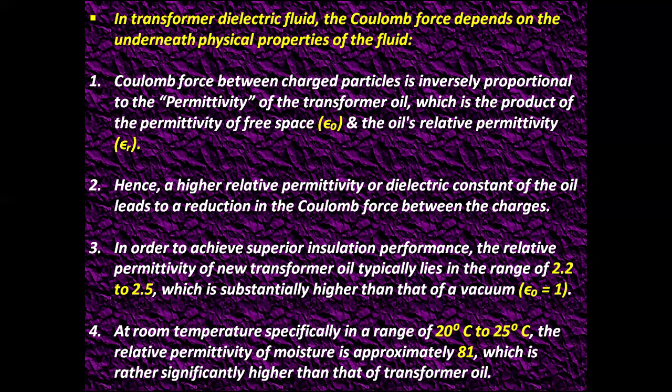1. Coulomb force between charged particles is inversely proportional to the permittivity of the transformer oil, which is the product of the permittivity of free space, that is epsilon 0, and the oil's relative permittivity epsilon r. Hence, a higher relative permittivity or dielectric constant of the oil leads to a reduction in the Coulomb force between the charges.